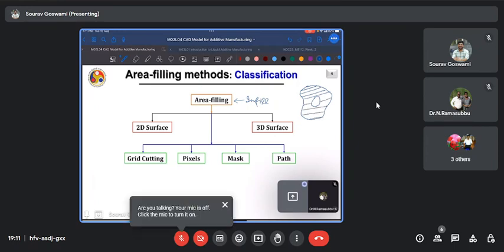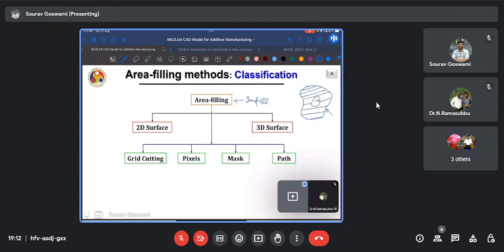For the external contour itself, or the internal contour for that matter, it is very easily done because when we have already sliced our STL file, we already have the contours. As Professor Sajin Kapil also discussed in his lecture, you know the points of intersection of the facets with any plane. So what remains is to just interpolate between these points and you obtain your contour.